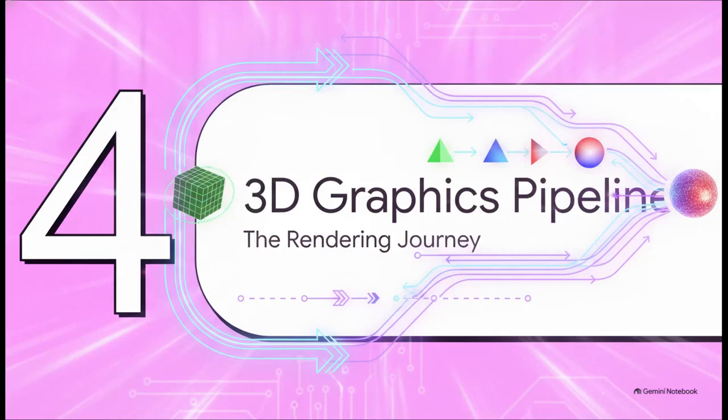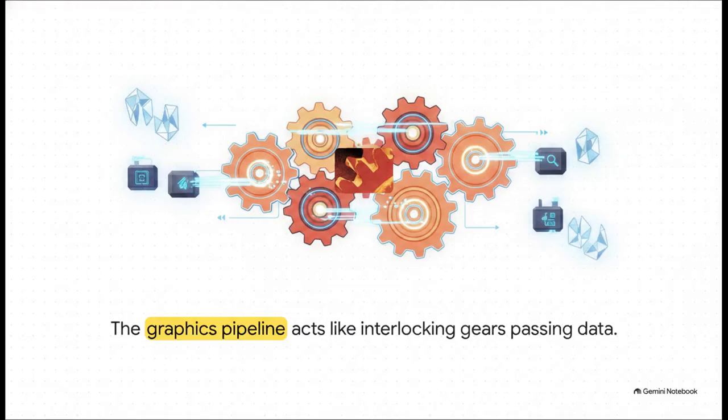Section 4. The 3D graphics pipeline. Historically, the graphics pipeline functioned as fixed hardware. If you were playing a 3D game back in the early 90s, the hardware was a literal assembly line, where data passed through incredibly rigid, unchangeable stages. But today, thanks to the unified shader architectures that emerged in the early 2000s, this pipeline is largely programmable. It acts like a sequential factory floor passing streams of data through both fixed-function hardware, like texture filtering units, and highly programmable software shaders running on those streaming multiprocessors we just talked about.